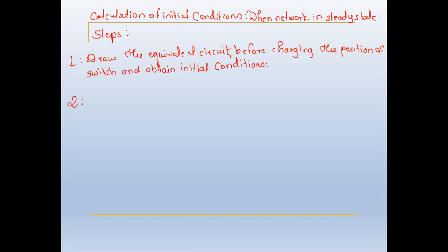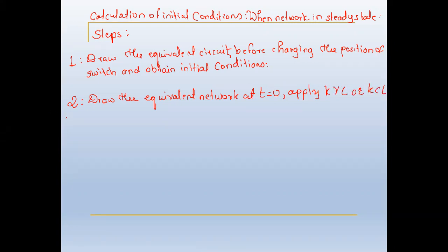Second, draw the equivalent network at t is equal to 0, apply KVL or KCL, calculate the required values.